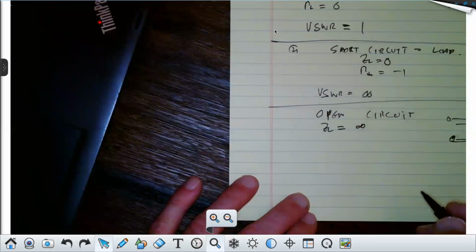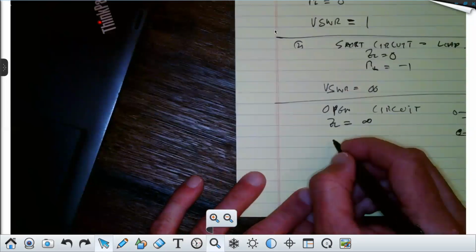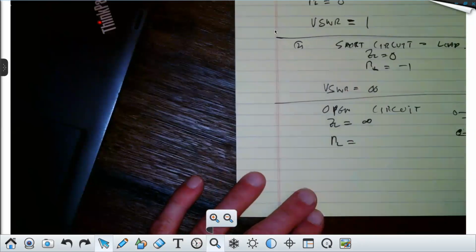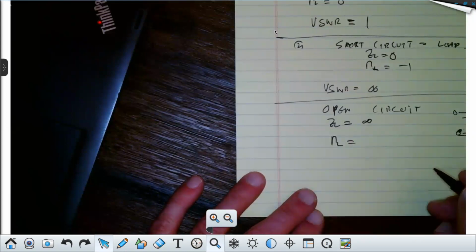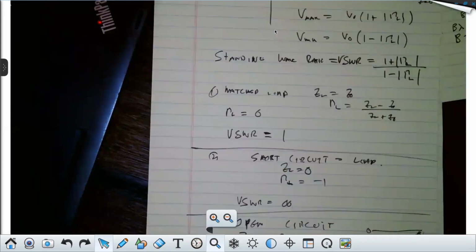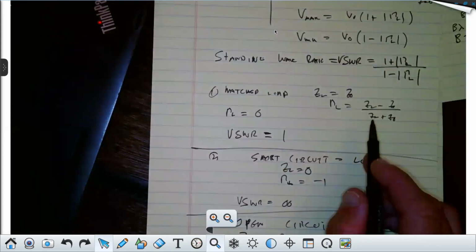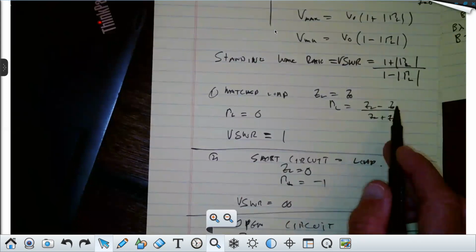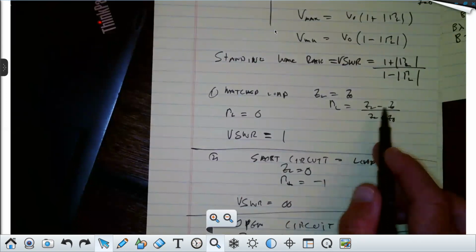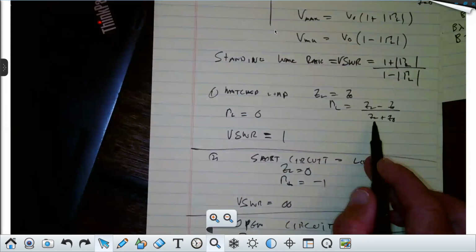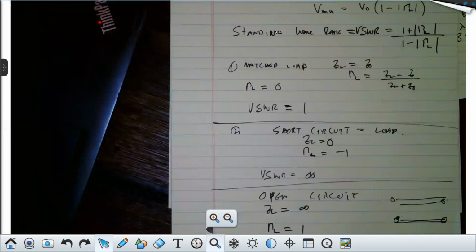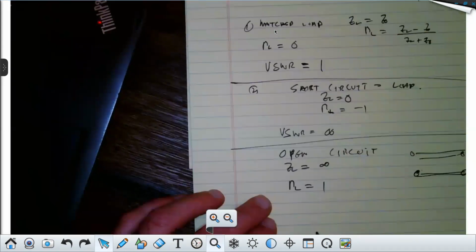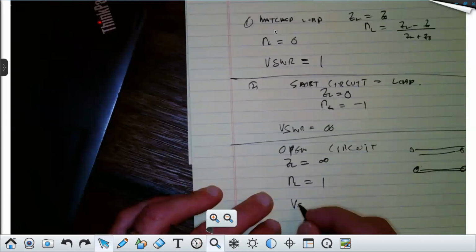So what would the reflection coefficient be if it has an infinite impedance, or an impedance tending to infinity? Well, look at the equation. This is the reflection coefficient, right? So if I have something tending to infinity minus Z naught, it's about something to infinity. And something tending to infinity plus Z naught, it's really 1, isn't it? Class? Y'all see that?